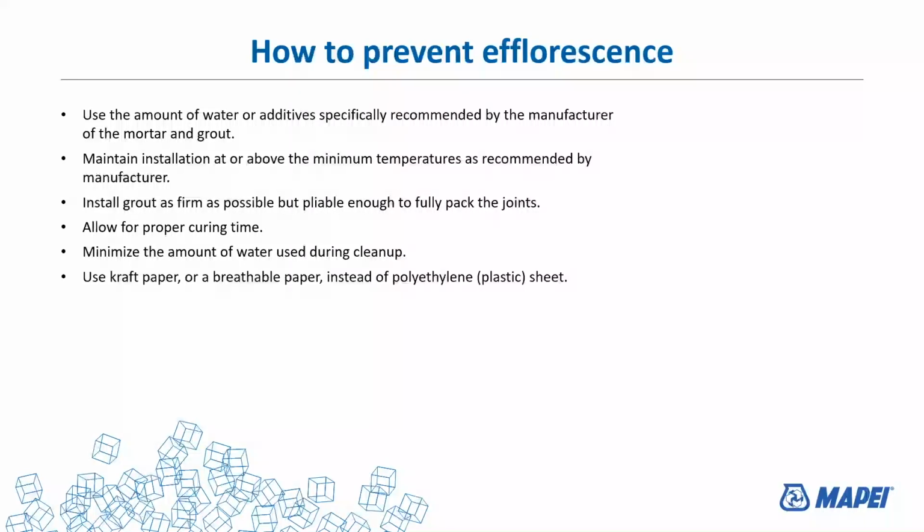When you've got high moisture content, doing moisture tests and moisture drive tests on the surface is probably the best thing to do. And then you have to revert to moisture mitigation type membranes when you have excessive moisture or moisture that exceeds the allowable rate for the application of any of these products.